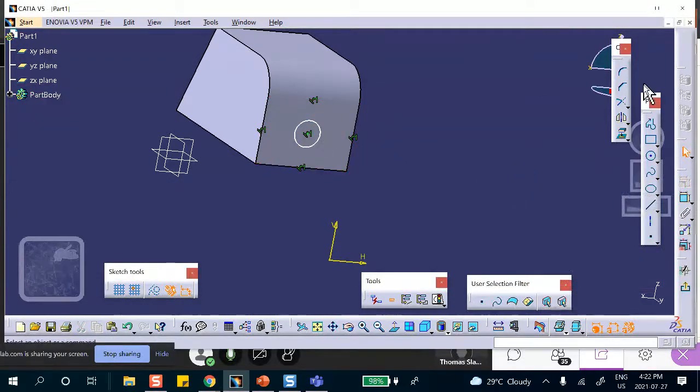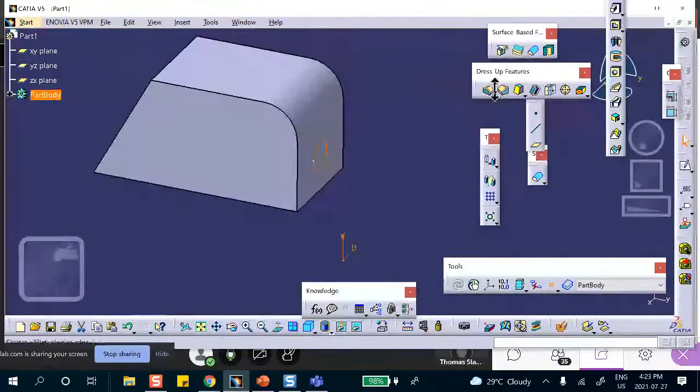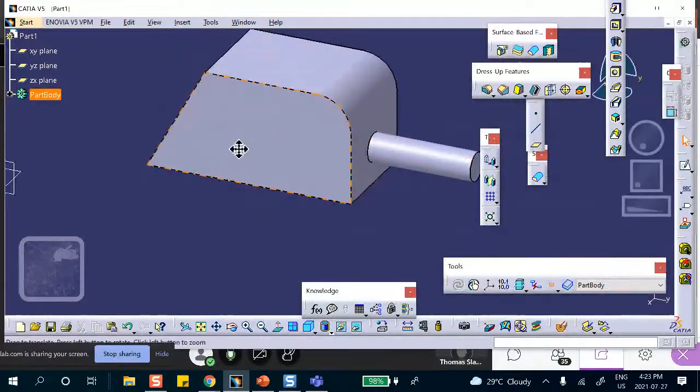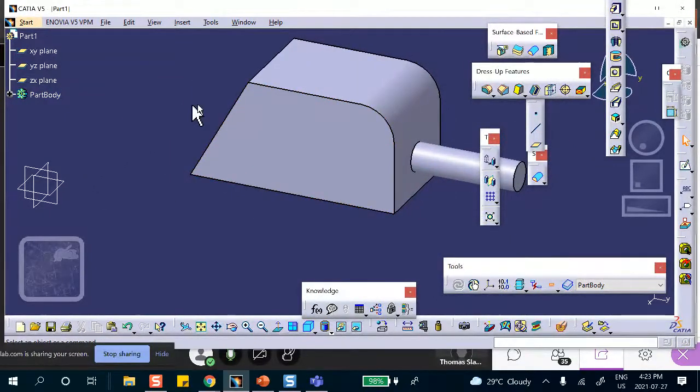And this radius is one of the things that I want to control in my design table. So dimension it. Right there. Exit. Pad it. Okay, good. So now let's go ahead and rename these. Remember, in the first example, first I created my Excel spreadsheet, and then I did the renaming. These are two different tasks. So let me rename these things. I don't have to do the spreadsheet first.